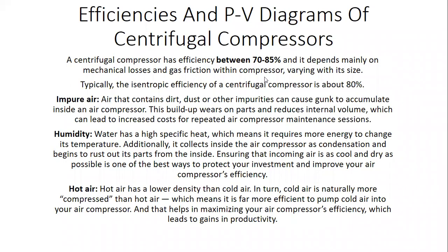Basically, there are certain factors that affect the efficiencies of compressors. Number one, impure air. Air that contains dirt, dust, and other impurities can cause what is called gunk, which is basically dirt, to accumulate inside an air compressor. This builds up wear on parts and reduces internal volume, which can lead to increased costs for repeated air compressor maintenance sessions.